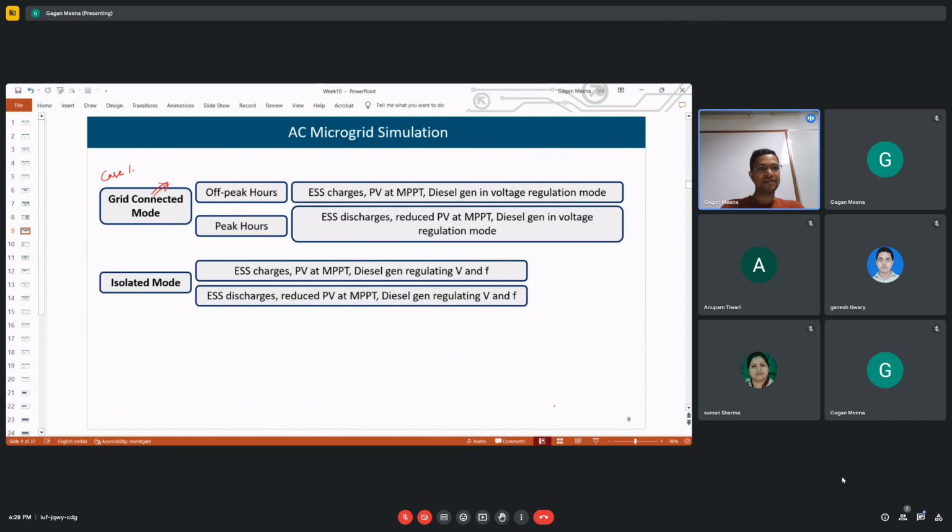If it is boost, 1:4; if buck, then 4:1. But these isolated types of converters can provide more than that. Here you see the 48 and 380 conversion ratio is almost 10 times. We cannot use these non-isolated DC-DC converters, and they will also not provide isolation.